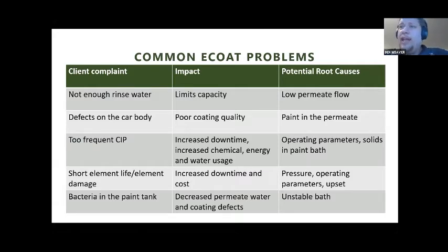Either clean the membranes proactively, introduce a high pH clean to help with the bacteria, maybe even a chlorine clean to kill the bacteria. So we know that upsets, we're always going to have them, but it's how we react to them and how prepared we are for the upsets to be able to react to them.